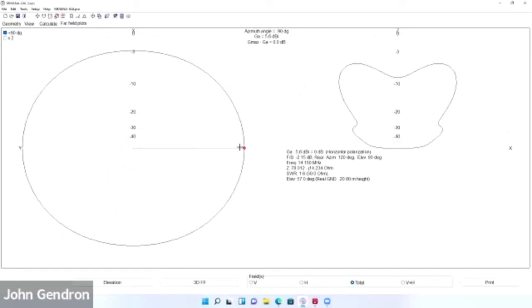Okay. Just those kind of things you'll find out when you start to do this, but don't get frustrated if you get in there and you design an inverted V antenna and you're like, I can't get my SWRs right. This thing works as a flat top. Why does it work as an inverted V? Capacitance. Okay. You're going to pick up capacitance off the ground.